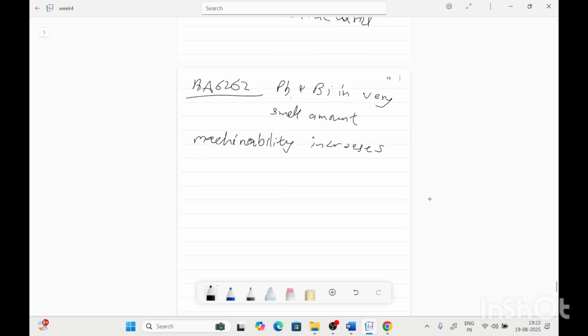And the copper is also present in this. Copper and chromium, like we talk: the aluminum, 1 magnesium, then 0.6 silicon, and then 0.28 copper, 0.6 bismuth, 0.6 lead, and some very small amount of chromium is also present. So the chromium present is the grain refiner. It acts as the grain refiner in the alloy.